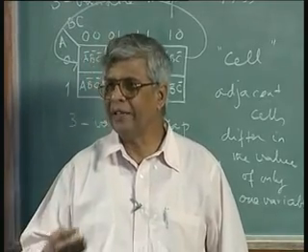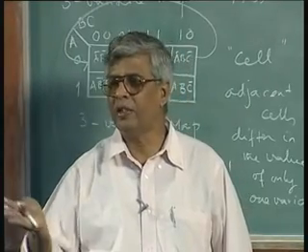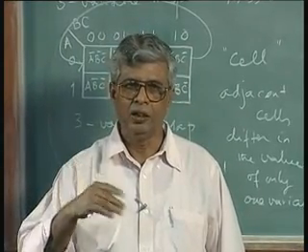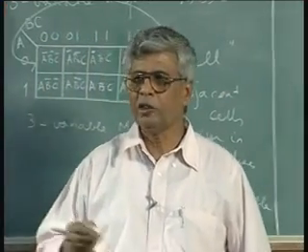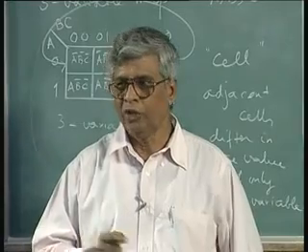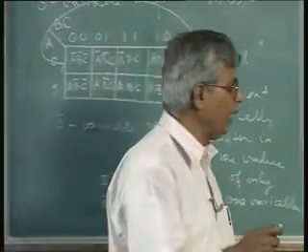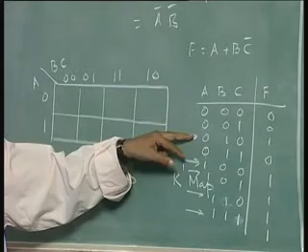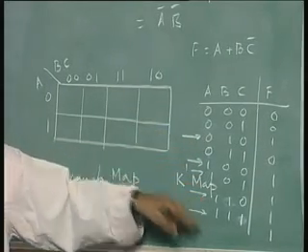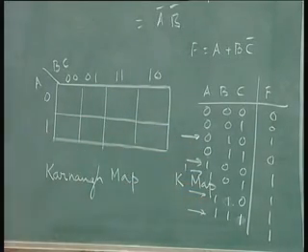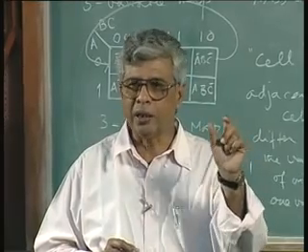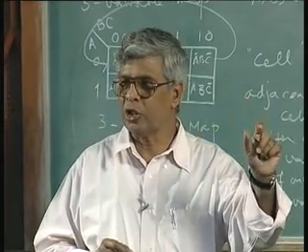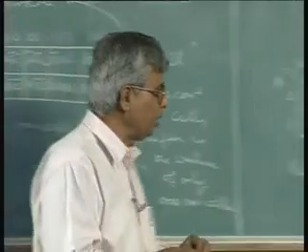Since we are going to be binary and we always have to have 0 as one of the values, in digital design and digital systems, wherever digital things are involved, we always start with 0 and not 1. So the first entry is always a 0 entry. So I will call this 0th row, first row, second row, third row, fourth row, fifth row, sixth row, seventh row. We also call these variations or combinations of the inputs min terms. Each of the input combinations of a truth table is called a min term. So the first min term is min term 0, the second is min term 1. As a symbol for the min term, a small m.